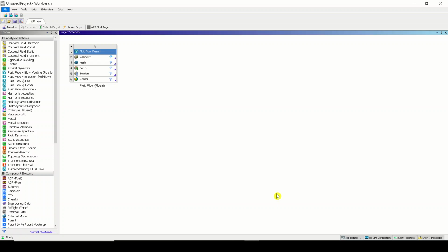So, in order to explain the procedure for changing the material, assigning it to the domain and performing that kind of simulation, we will be dealing with a simple project in this workshop. I will be creating a simple circular cross-sectional pipe of some random length, and we will be performing a fluid flow simulation of different materials. For example, we will consider water or other oils. The main objective is to understand the procedure to assign that particular material and perform the simulation.